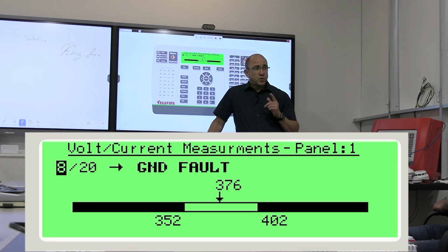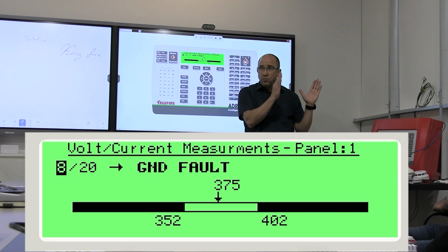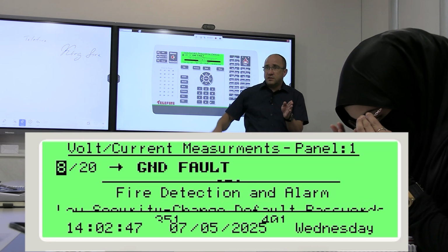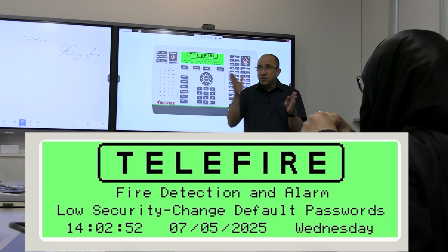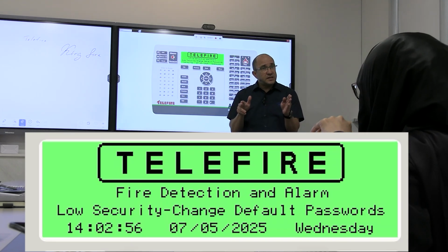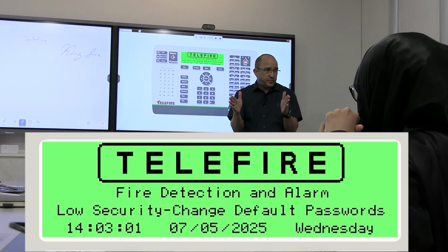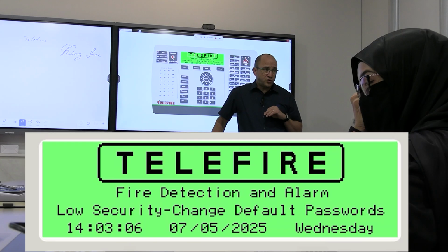Also here, you know that it's one of the areas. You go to the middle, more or less. You disconnect the wires. If you see the graph moving, and it's perfect, so you know it's from here towards the end. You connect it. Now you go again to the middle. You connect the 2 wires. If you see this ground fault, so you know it's from here to here. It's much easier. You have the signal. You can find it straight away.